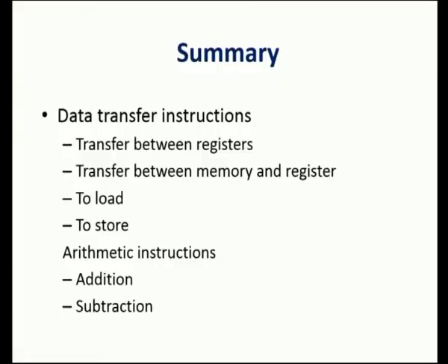In today's session, we have discussed data transfer instructions and arithmetic instructions. In data transfer instructions, we have seen the instruction formats to transfer data between registers, transfer data between memory and register, and how to initialize and store the data. In arithmetic instructions, we have discussed addition and subtraction with carry and without carry, including increment and decrement of register or memory content.